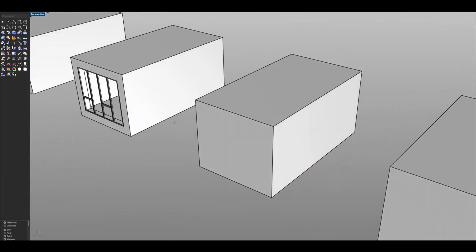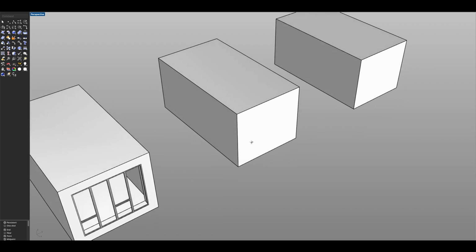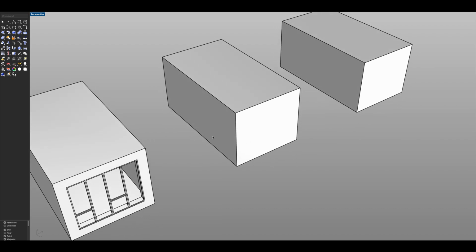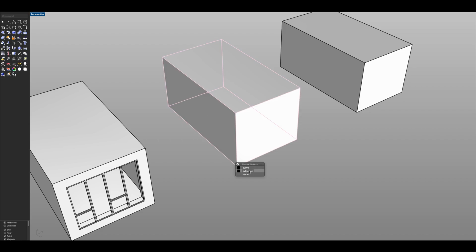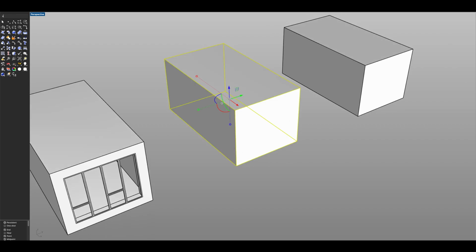Now for our balcony container. To start off, I'm going to draw a line here all the way to the other side, but I just want to give it a measurement of about 1.2, which will be our balcony's width, like that. Enter. Okay, it's there. Now we just need to click our main brep here and go for scale 1D.